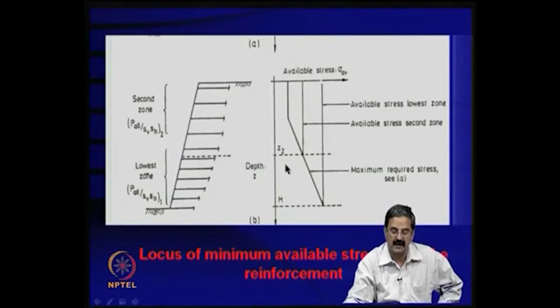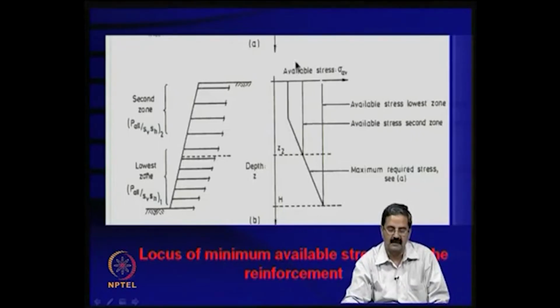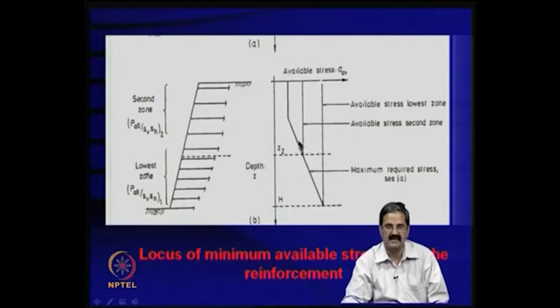So, what we do is, depending on the availability of the material, we will try to choose some material which is something better, but then it can be of cheaper cost, cheaper and less strong compared to the previous one. So, this way you can really understand this whole concept and see that at any stress level you try to keep the reinforcement satisfactory, and in the sense of that limit, always the available stress in the reinforcement should be more than the required stress. Okay.